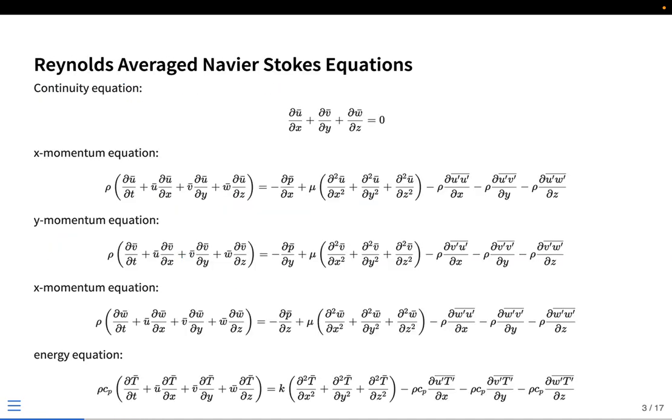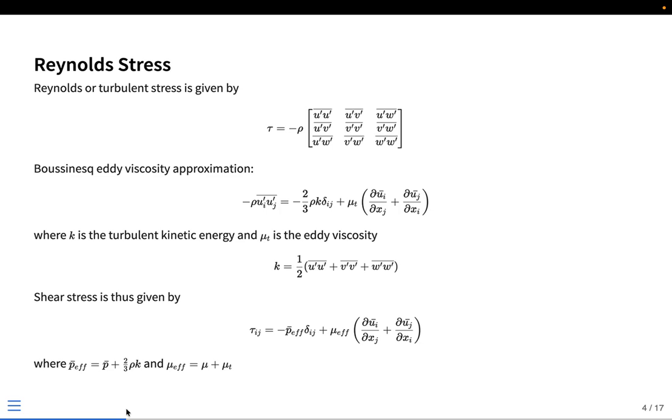So you have the Reynolds-averaged Navier-Stokes equations, where I have written them down for a general case, but then some of these terms would actually turn out to be zero. Followed by what exactly the Reynolds stress is. These are the additional stresses that are imposed because of your random fluctuations. What the viscous term does is it tries to homogenize or mix the fluid together, so that velocity gradients turn out to be zero. So what these fluctuations are trying to do is mix the fluid together.